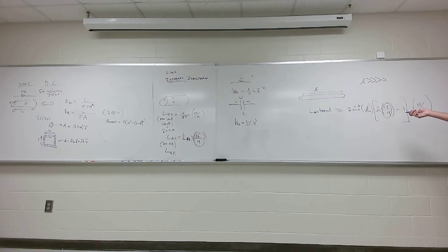You'll notice there's nothing said in here about the return path. Right? So this partial inductance they justify by making assumptions about the return path. One is that it's in proximity. But I'm going to tell you, this is just one of many formulas. The only way you get the real inductance, the external inductance, in a wire is by knowing the entire path the current takes and then modeling it. You can do simulations to get that, all right? But I'm going to tell you, it's not easy.